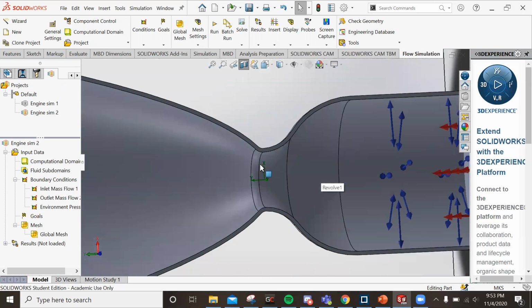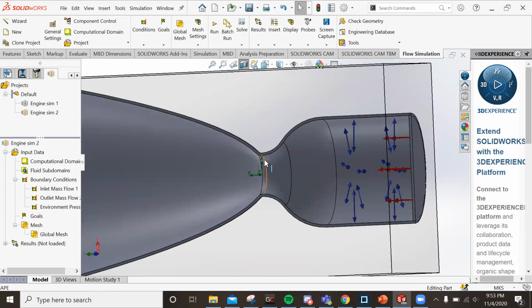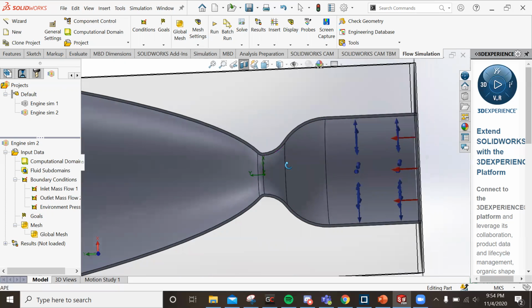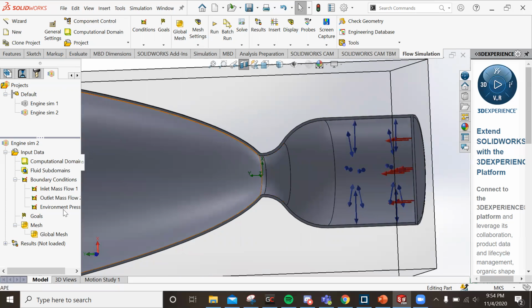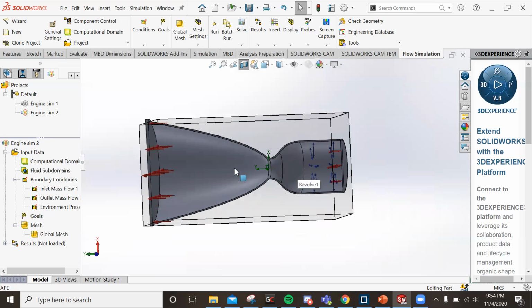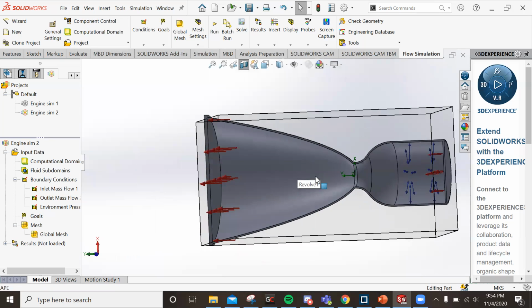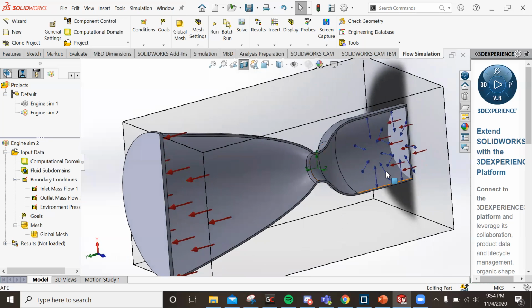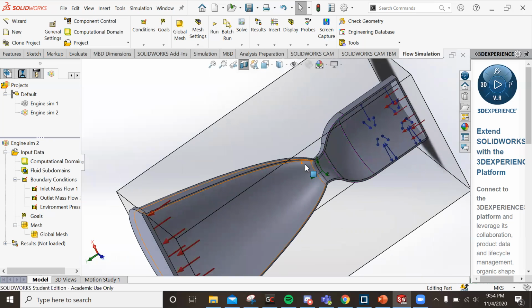But for example, if you wanted to define a surface at the throat, you'd get the mass flow rate through that surface, or I don't actually know what else you can get from goals. I think goals will also give you a detailed breakdown of what the values are for each iteration instead of just an average of all the iterations of the sim, which I should probably explain.